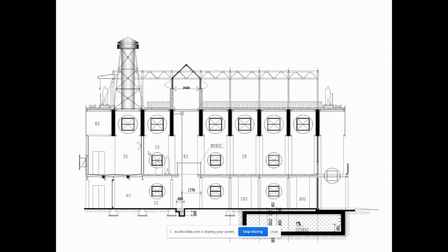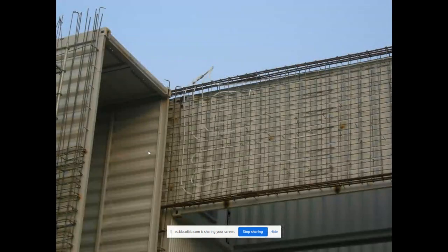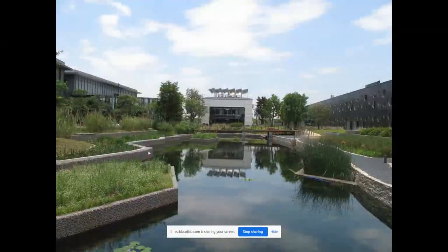He makes these waterfalls in cold water. Now, there are the beams with the pipes in them being laid, before the concrete's poured, and the cold water will be circulating to cool down the beam, and the beam then is a radiant cooler.